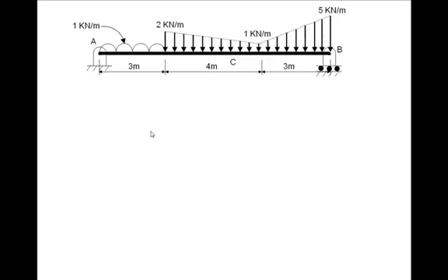Okay, look at the next problem. Here, the loading on the beam AB is quite complicated. You know, there is a uniformly distributed load and there are trapezoid loads. So we have looked at this loading in this manner, as if this one is throughout and then there are these triangular loads. Now, we are going to put the equivalent of all these loads. And we are going to replace the supports by appropriate reactions.